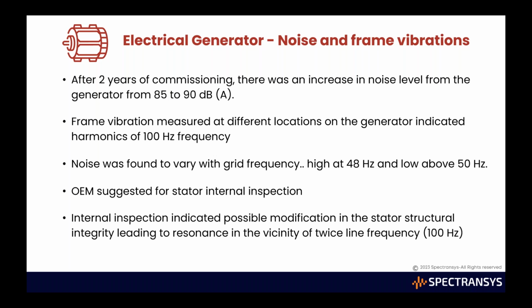And when we did the vibration survey and took the spectrum, it was showing 100 hertz as the dominating frequency, and its harmonic content 100, 200, 300, like that. The machine is an electrical generator. In India it is 50 hertz, so it is operating at 3000 RPM, and 50 hertz is the 1x component. But on the frame vibrations, there were no 50 hertz components present. They were all 100 hertz and its harmonics. So basically it suggests that there are electrically oriented sources present in the machine.